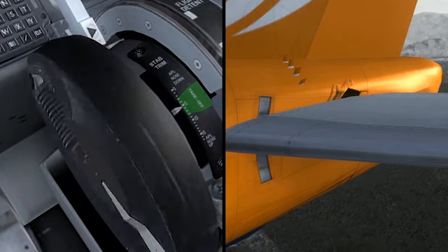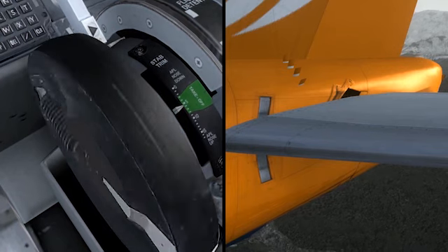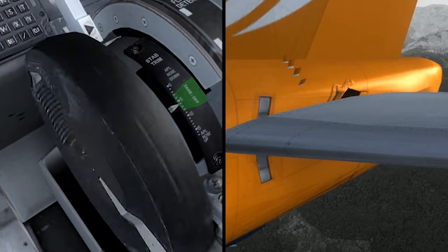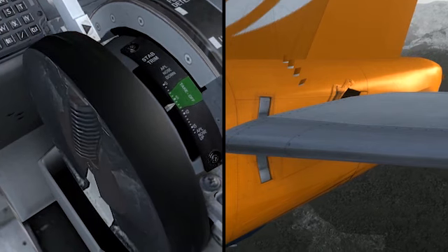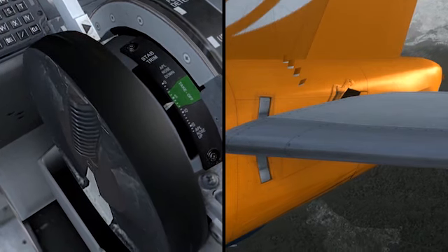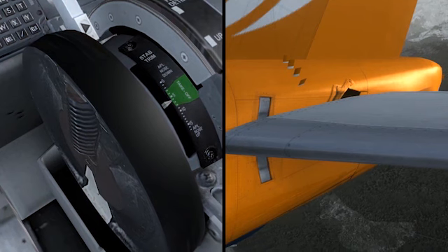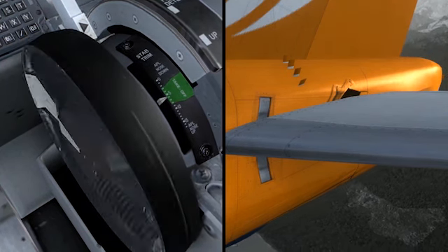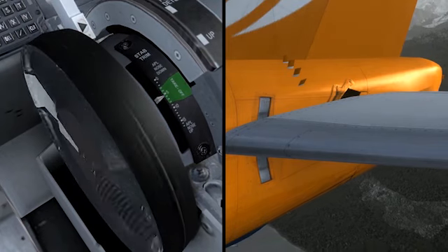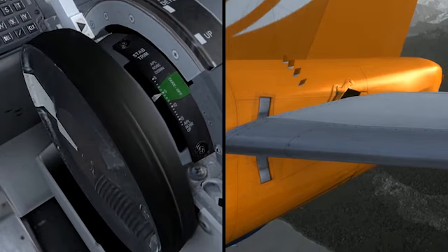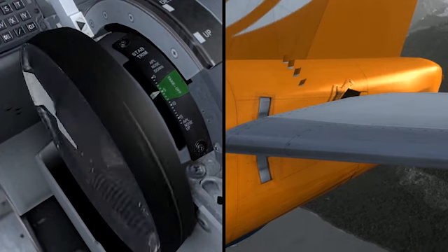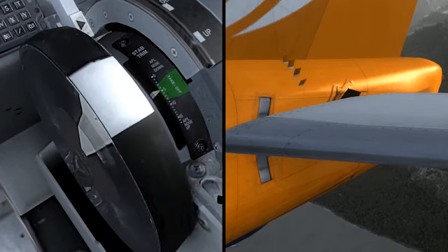Finally, during autopilot operation, the digital flight control system gives electric input to the stabilizer trim actuator. However, this actuator operates at different speeds when receiving autopilot input. Stabilizer position sensors feed the DFCS. Sensor A sends information to the DFCS via the Flight Control Computer, FCC, A. And similarly for sensor B.